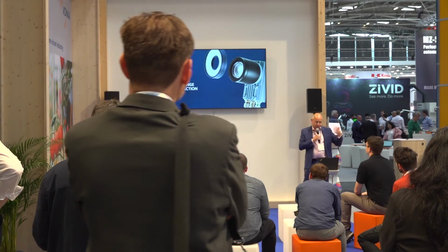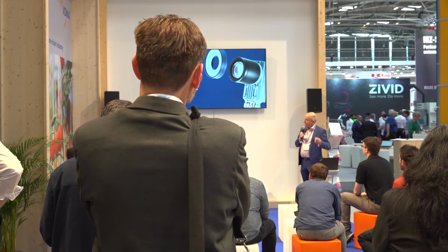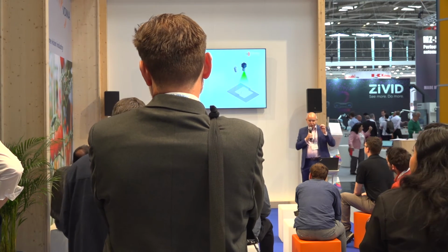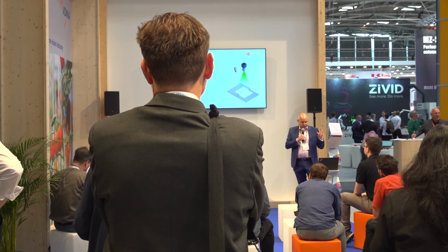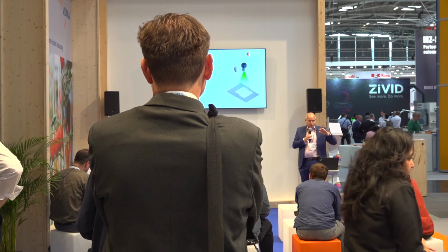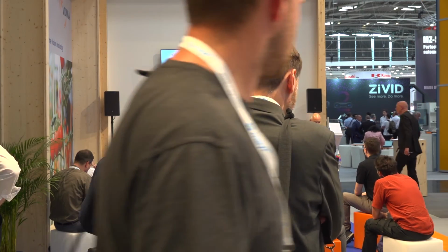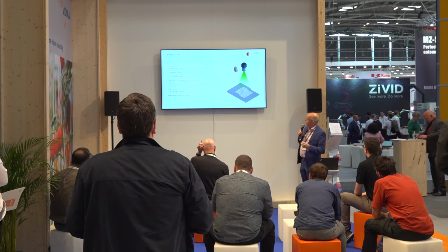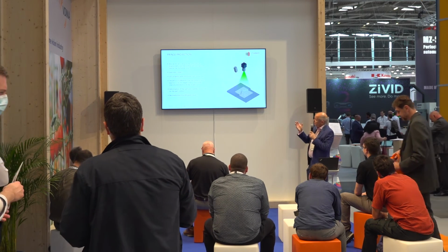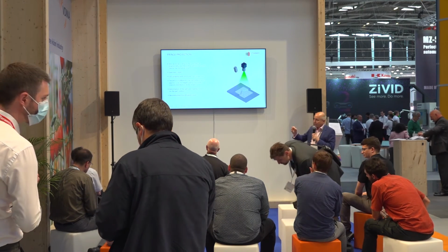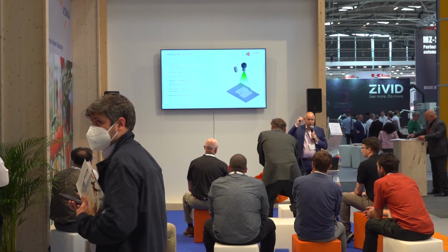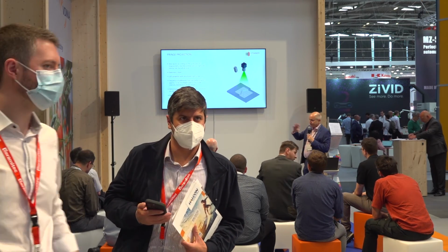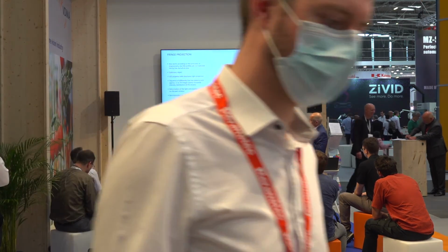So then we move on to a different technology, fringe projection. Still triangulation, but this time we're talking area scan. But if you remember what I said on the stereo, resolution was mid. If you want to improve that resolution and get it more, we then start to look at this. Now, what happens here, the object has to be stationary. Instead of having a laser, we have a projector. And we project lots of different patterns onto the object and do that stereo vision on that pattern data.